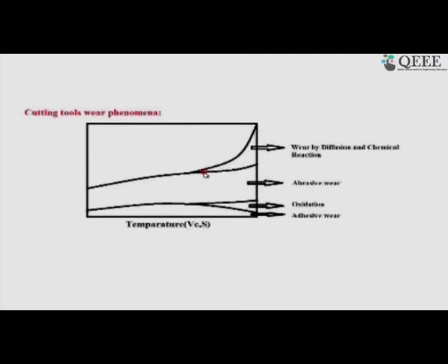Now, the material of the tool is showing its weakness against chemical attack. Abrasive wear means a mechanical attack, which because of the loss of hardness may also be aggravated, but here because of the rise of temperature, all this chemical reaction or mutual dissolution like a salt and solvent may also take place, and finally, there will be a transportation or movement of the material across the interface, and this is by the process of diffusion.